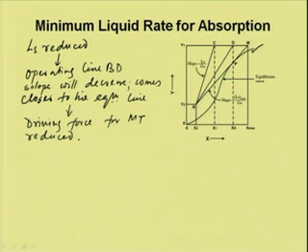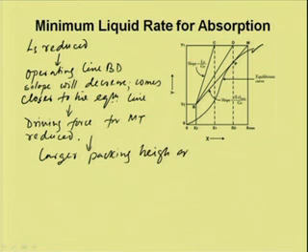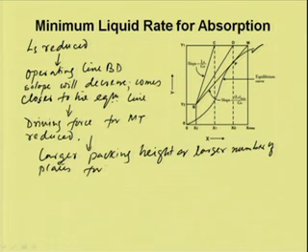So, if the driving force is reduced, we need a larger packing height or a larger number of plates for a given separation.